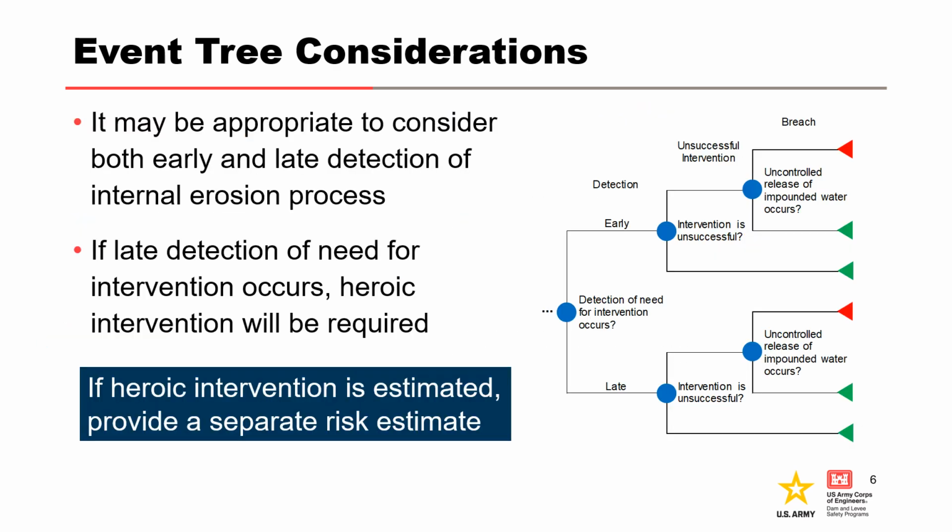It may be appropriate to consider both early and late detection of the internal erosion process. If late detection of the need for intervention occurs, heroic intervention will be required. If heroic intervention is estimated, you should provide a separate risk estimate because it would be irresponsible of a dam or a levee owner to manage a project or portfolio of projects based on the estimated risk assuming heroic intervention.